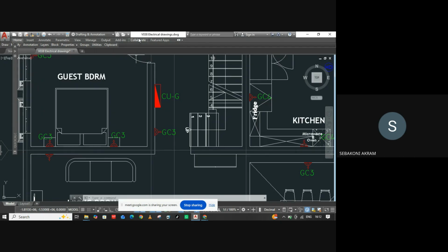So it is preferable that if you calculate your load and it exceeds 120, you go to three phase. Are we together? And for three phase distribution, this is now changing from a consumer unit to a distribution unit. We together?